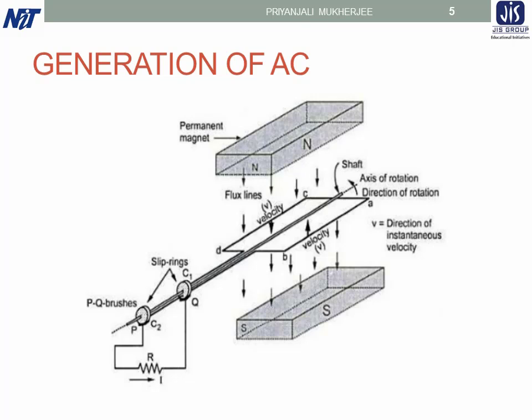The EMF generated in both cases has a sinusoidal waveform, and the magnitude of the EMF generated in the coil depends upon the number of turns of the coil, the strength of the magnetic field, and the speed at which the coil or magnetic field rotates. The first method is employed in small AC generators, and the latter is employed in large AC generators.